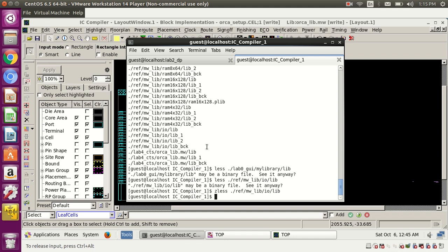Don't confuse. I'll explain. I have said there is a flop here. There is a D pin, the data path, and there is a CK pin. This CK pin will come from the clock normally. But what we have added is an extra clock gating cell, and for the clock gating cell we have added an enable signal. So you said this clock gating cell is an AND gate. Forget about this logic and that logic. What this cell does is it has to give a clock to this. So the output of this clock gating cell should be a clock period. That's it. You said the AND gate will serve this logic.